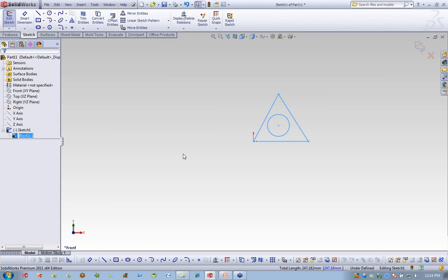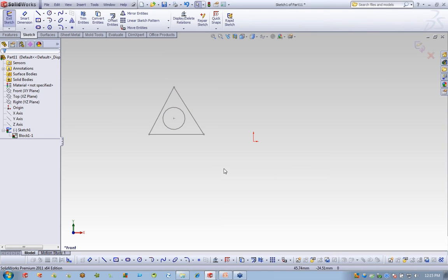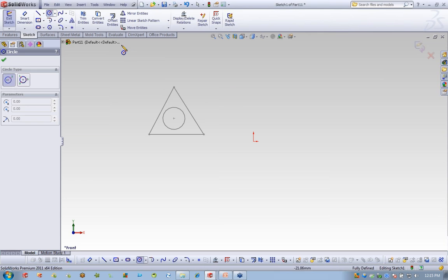Now, once I've created the block, all of these entities are movable all as one big chunk. Okay, I can drag them around the screen. I'm not worried about constraints of my sketch, lengthening of my line. You know, I didn't even fully constrain or dimension this particular item. Now, it will show up as a subcomponent to the sketch, as a child to the sketch. And I can continue while I'm still in this sketch creating more blocks if I'd like to.